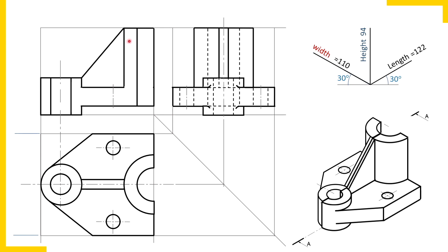The newly generated surface, this rectangular surface where right now a red dot is, and this surface, that is hatched portion. This is hatched portion and this is hatched portion. Hatched portion means newly generated surface where we draw hatching lines. Now once again to remind you, this is inner surface of the hole. We should draw hatching lines only on newly generated surface due to cutting. Inner surface of the hole is not surface generated due to the cutting.